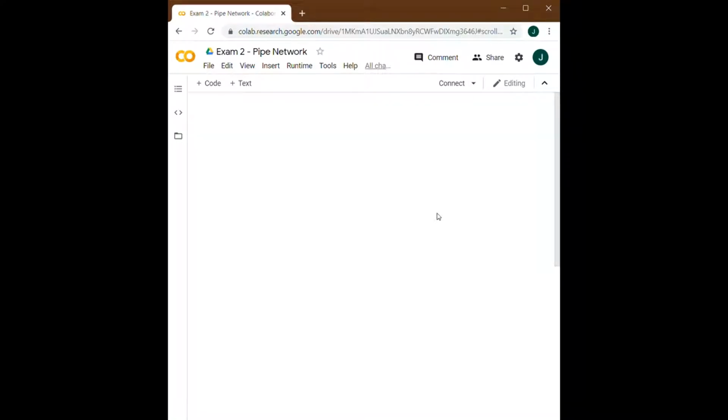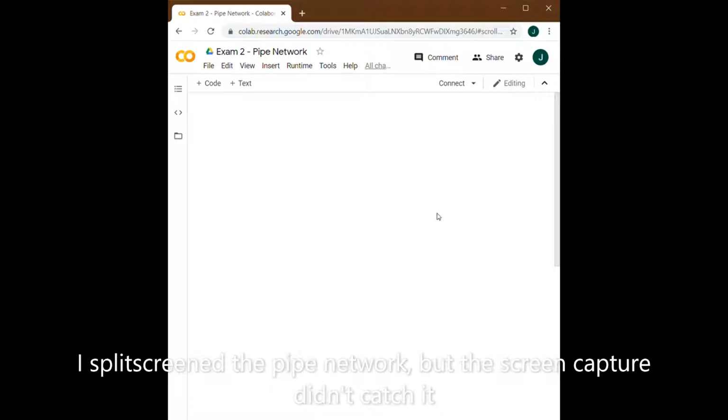Today we are going to examine pipes that are flowing in a network. This video is going to be split up into two parts. Part one, which is this video, is going to create functions to calculate head drop and flow rate through a pipe. So in a single pipe segment, we're going to calculate head drop, change in head, and how to calculate Q, or flow rate.